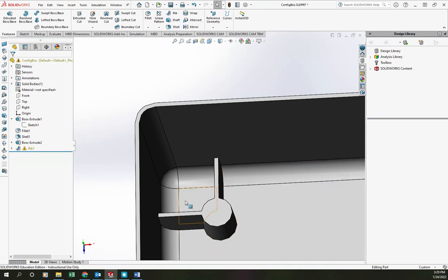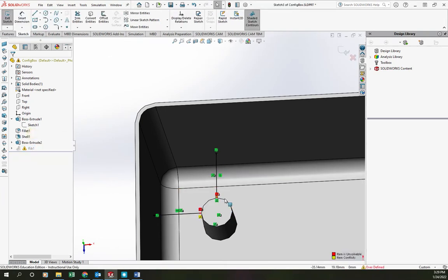I want to add a hole for an M4, or maybe an M2. I have an M2 in the handout. Let's look and see what it looks like, it'll fit good. So let's draw on that again. Oh, my rib has an error. Probably those edges got converted and they weren't there anymore. There we go. Fix that.